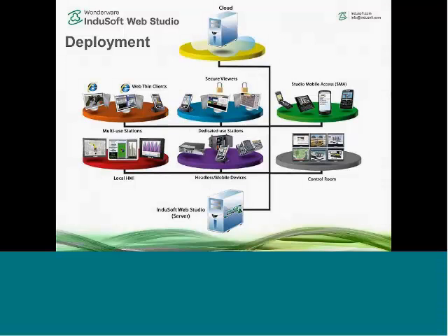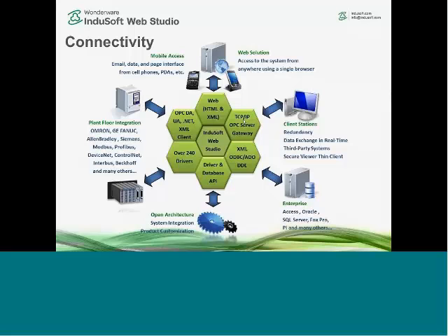But really interesting is, I think one of the largest I've ever seen anyway has been 8 70-inch monitors connected together, and that was very, very impressive. The gentleman standing next to it looked very, very small next to 8 70-inch monitors. But there are lots of different ways to deploy this product, and it doesn't have to be a single HMI talking to a single PLC. There's lots of network solutions. You can have machines with your HMIs running InduSoft, and then a server acting as SCADA, data collection, lots of different ways, even through the cloud.